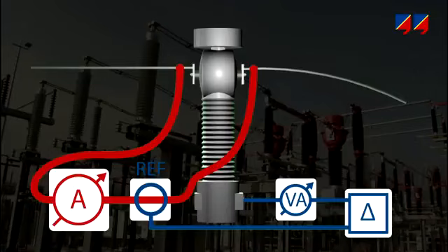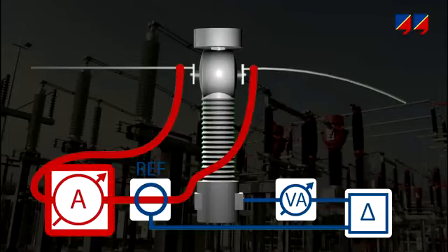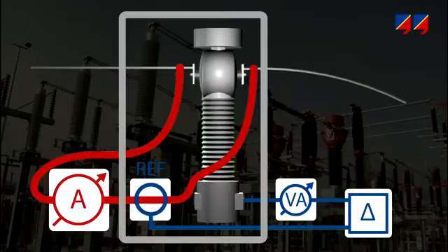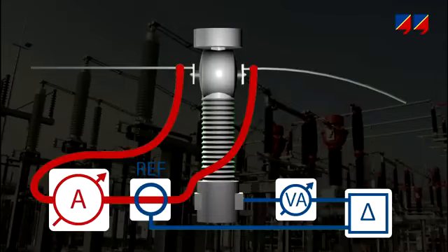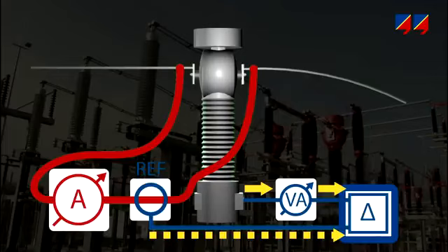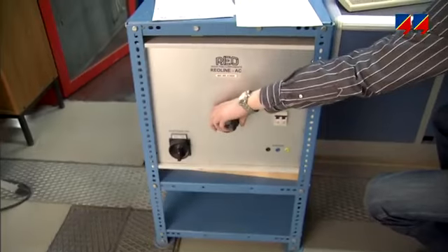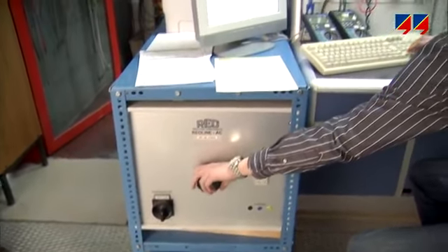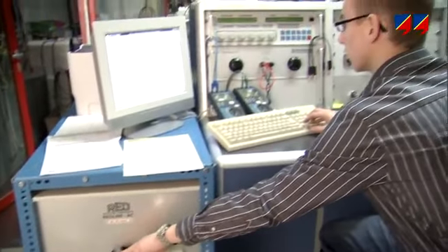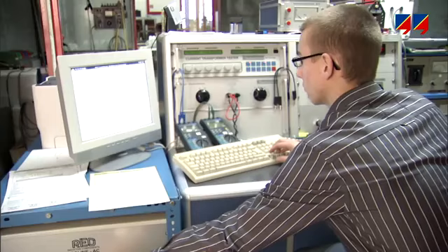If a CT is to be comprehensively tested in a classical manner, the current bridge method is used. Through a high current source, defined values of primary currents, from fractions to multiples of rated current, are injected into a reference CT and the CT under test, which is connected to a controllable burden box to simulate different load conditions. Via a measurement bridge, the output currents from both CTs are compared in amplitude and phase. With this method, all current and burden value combinations defined by the relevant international standards can be verified, and the CT's compliance can be assessed.